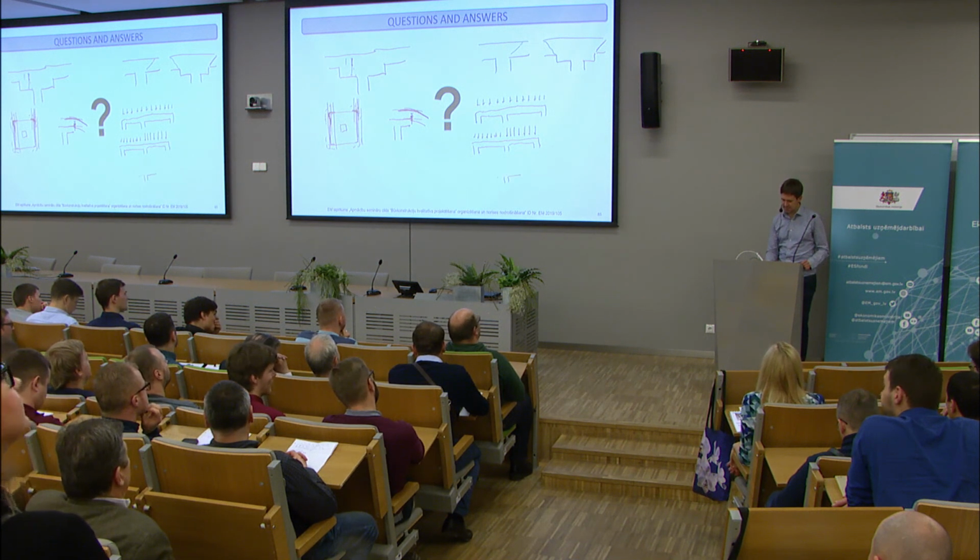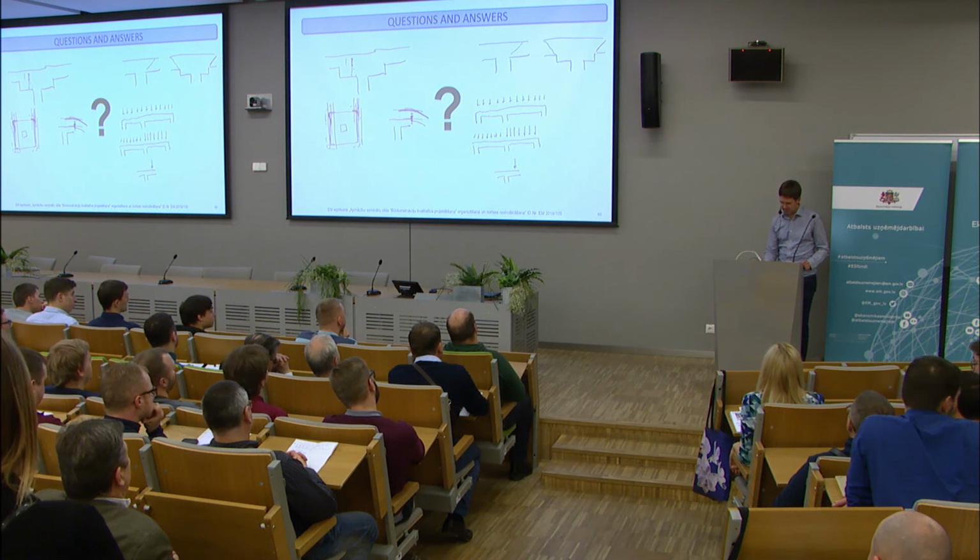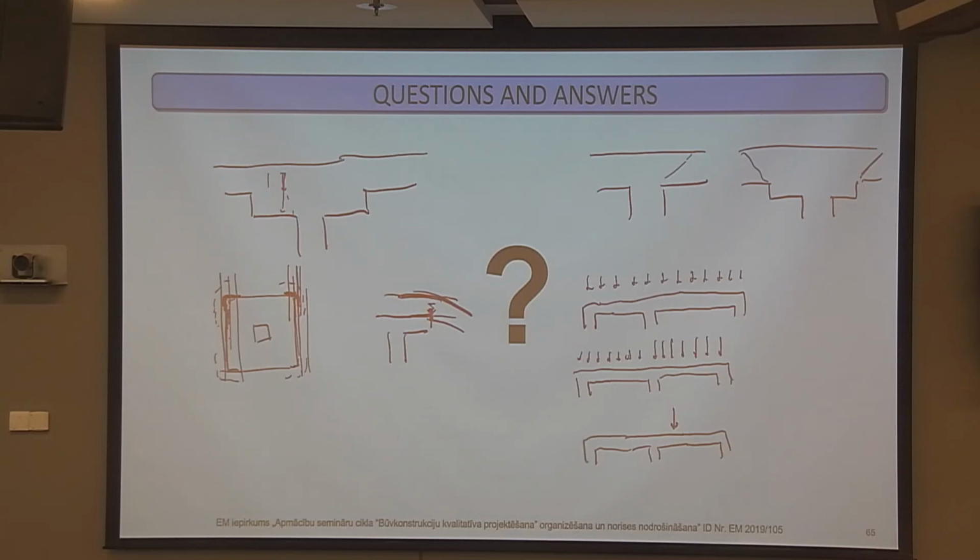Yeah, I made some sketches in here. Eurocode would look at all these cases the same way, where the only parameter would be the unbalanced moment at the column. But actually, the distribution of forces on the control perimeter is different. Like in this case, where you have different spans, and that's why it's unequal.